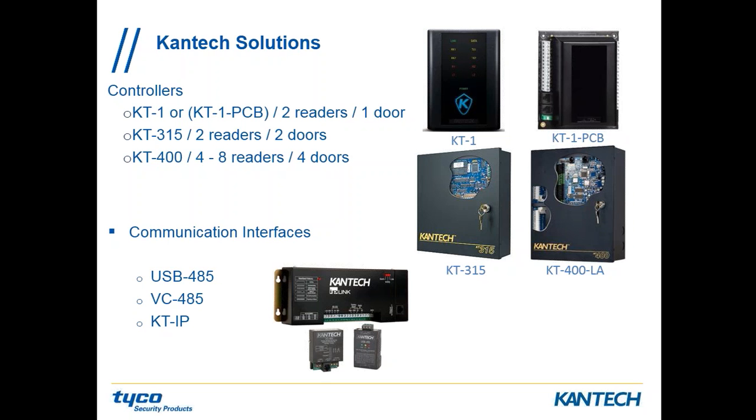This controller comes with both outputs, one for the maglock and one for the door strike, and it has 4 inputs available for any other device, like a door contact, motion detector, whatever you might think of.